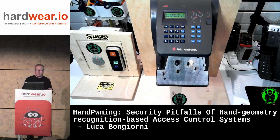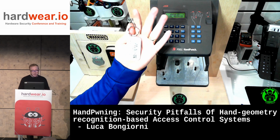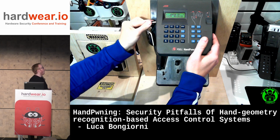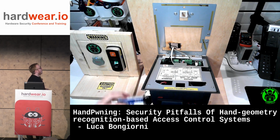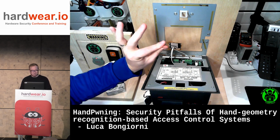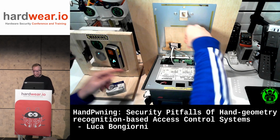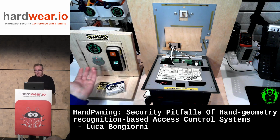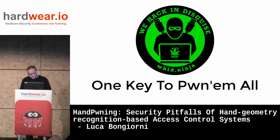No alarm will be triggered because there is no anti-tamper switch. And then with the classic MacGyver-style paperclip, we can trigger the relay that will open the lock. So it's the classic paperclip thingy, and you just need to pull down, to ground, that pin, and the door will open. So all this set of things is leading to good times for red teamers out there.